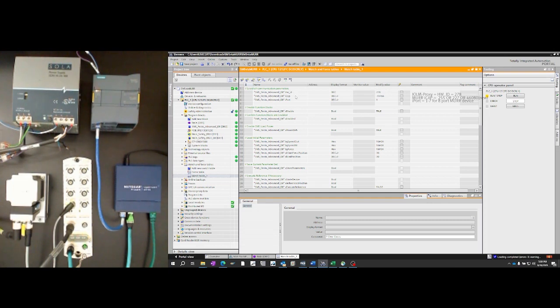The second piece of information you'll need is the ICAP. This is a vendor-specific number that's released from the IO-Link organization. There are 3 IO-Link ICAPs for MURR Elektronik. Those values are 255 decimal, 227 decimal, or 46080 for newer versions.